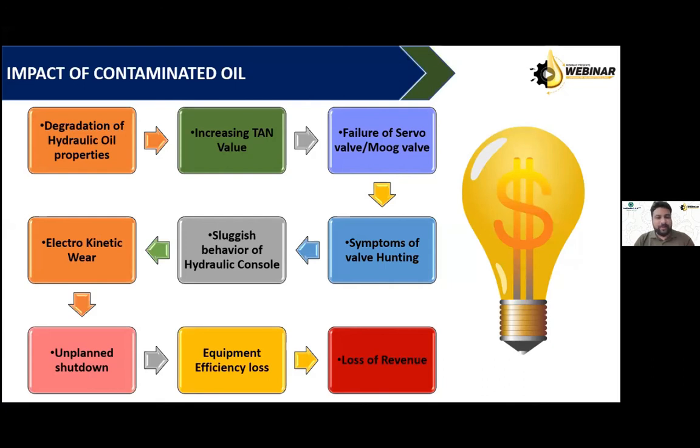ultimate job for you. Take an example of a wagon tippler, which tipples the entire bulk material of coal or some other mineral. And the function depends on the movement of a hydraulic motor. Now, this hydraulic motor gets its high pressure hydraulics from a particular valve. And if the entire line components fail, then probably your tippler would be stuck in a position where you can neither unload it, nor move the rake out from there. So it might lead to time loss for you. It might lead to production loss for you. It might lead to entire operational inefficiency for you.